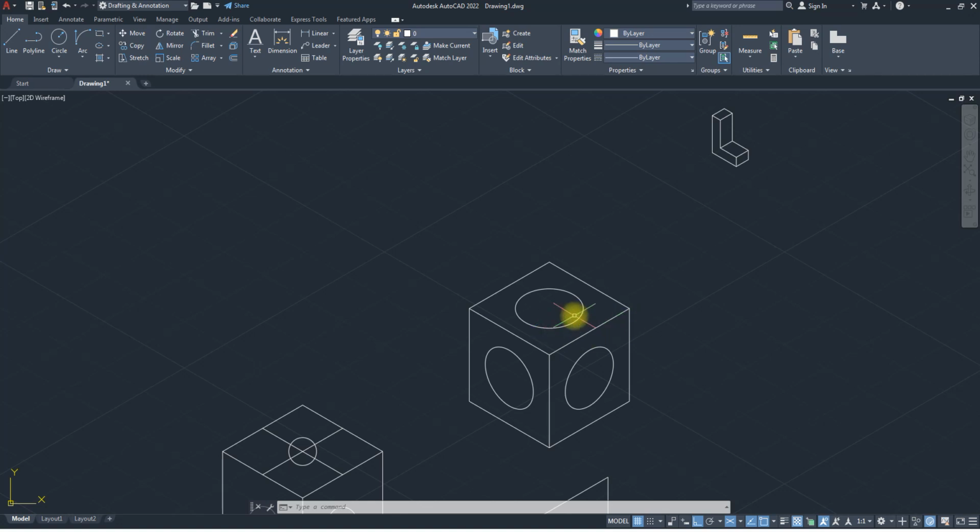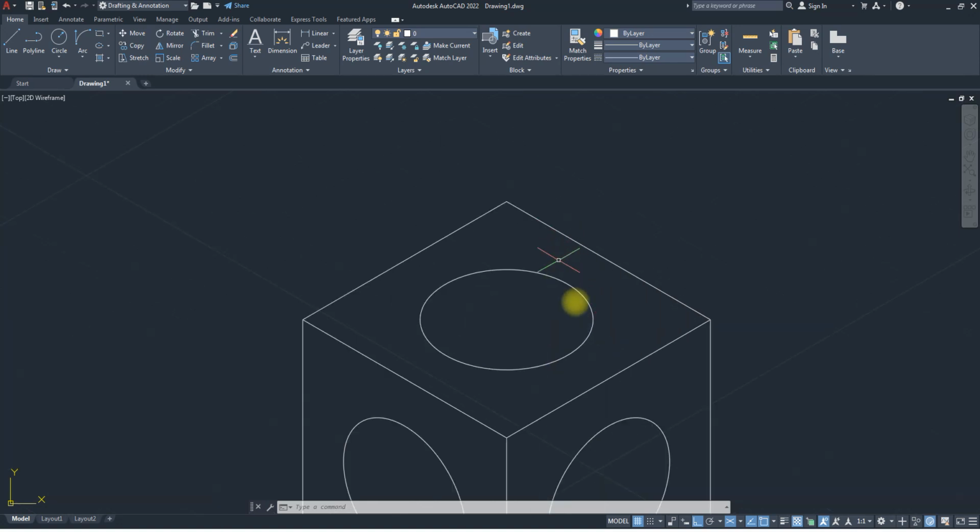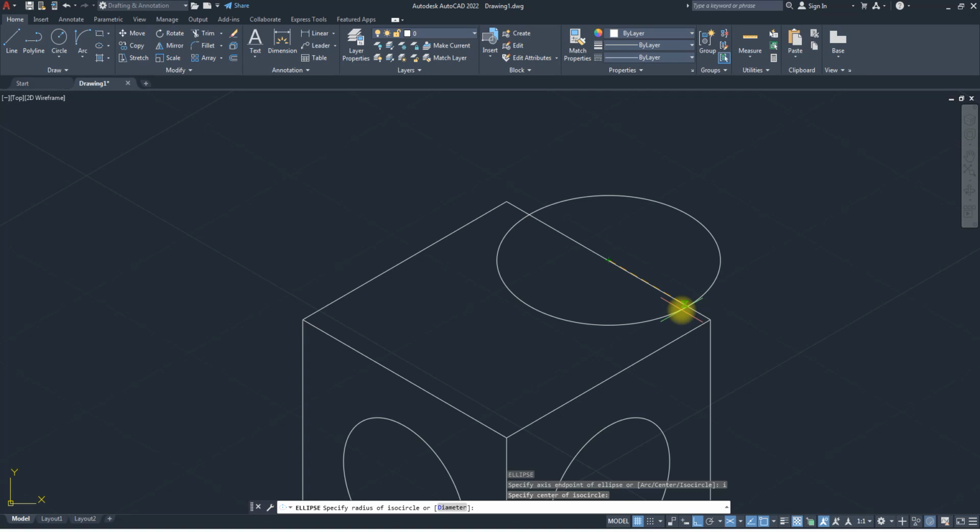Like I also said, you can also use your modifier tools, right? So that means, like I said, I want to have a chiseled top here. So that means if I'm going to be having a chiseled top, I need to create an ellipse in my top view, right? So instead of me bringing it from this center point, this is going to be my edge. Okay, so I'll select this, delete, run my ellipse again, I for isocircle. So my center point will now be on this guy, draw it all the way to this place.